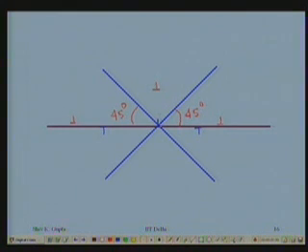Why is this going to attract? Here and here, these will attract each other. They will try to arrange one over the other. Can you see that? When I have a dislocation like this, I have tensile strains here.